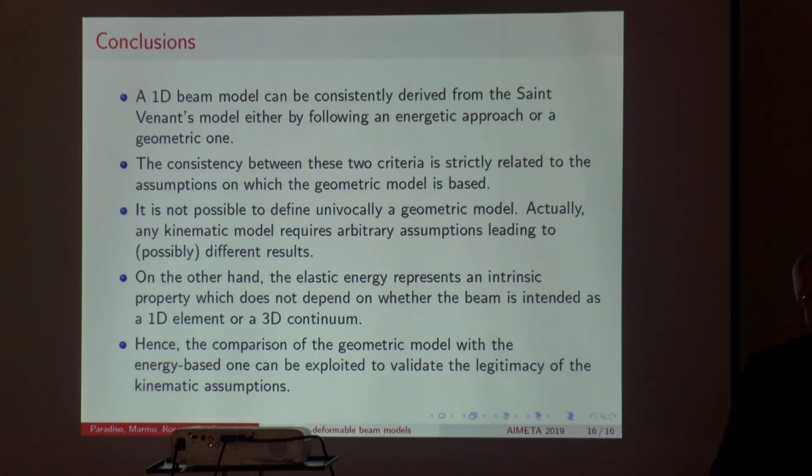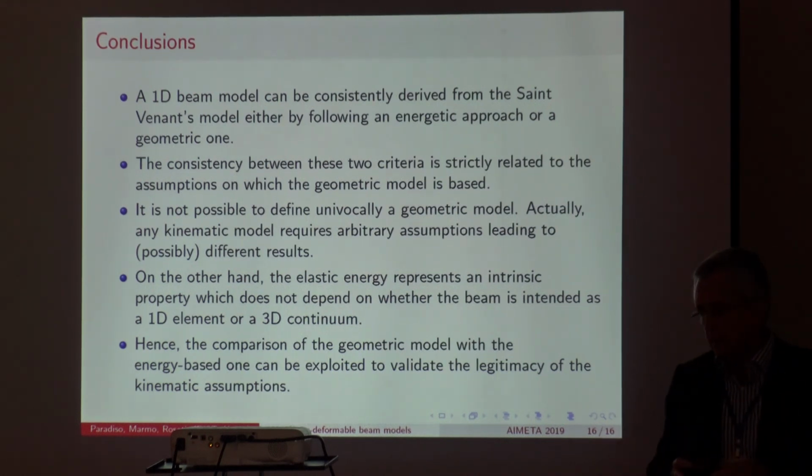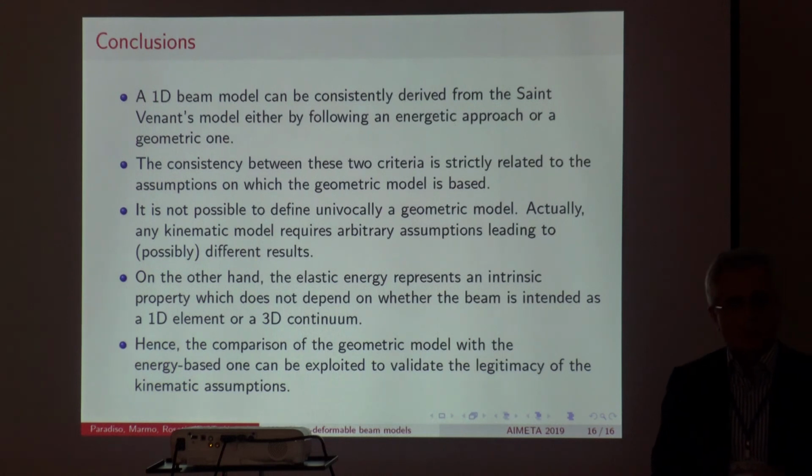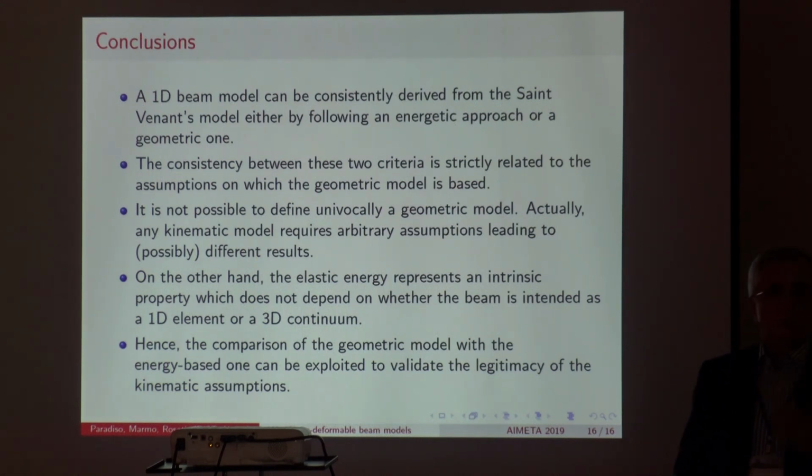In my opinion, the concept of center of shear is an elegant way to say that shear and torsion can be divided, but you have to discard the concept of center of shear. I want to refer to the center of twist because it is a geometric quantity, univocally defined, depending only on the shape of the section, not on the elastic properties of the material. In my opinion, of course.